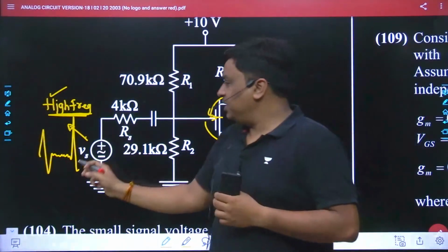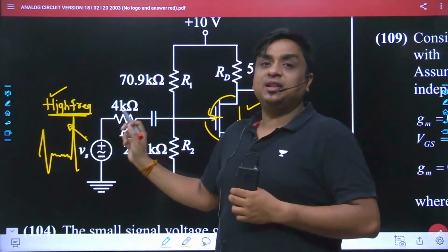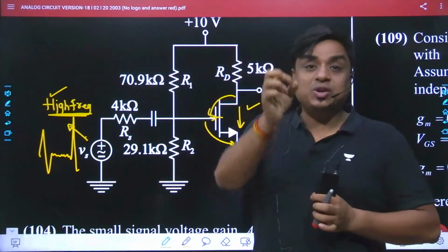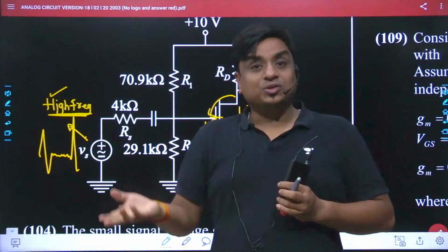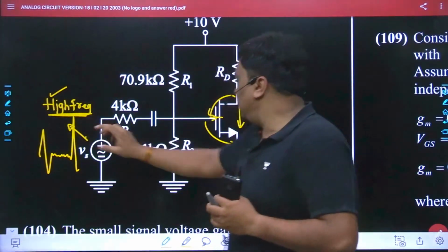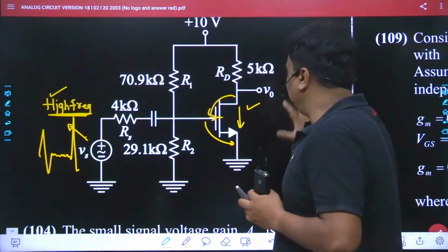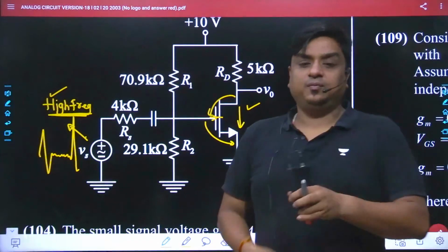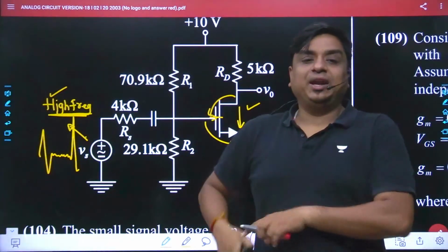So what can happen? If you apply a large signal, the MOS may not work in the appropriate region where it actually works as an amplifier. If it goes from saturation into the cutoff region, those parts of the signal would not be constructively reflected at the output side. So you will be getting a distorted outcome. Yes, you will be getting a distorted outcome.